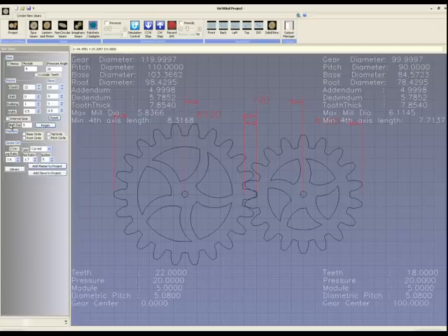These shaft holes only really show up in terms of milling the gear in 2.5D, in which case we'll cut out that hole during the G-code process. They're also put out as the size of a hole in your side, front, and top and bottom plates. DXFs are put out for those plates by the output manager when you generate your gear profiles.